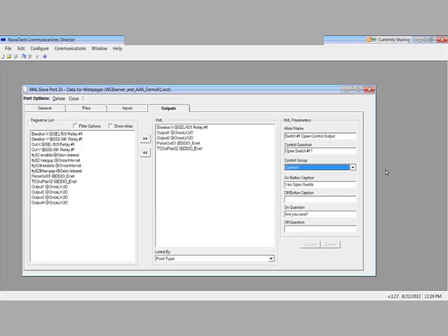And we could go into that in a little bit more detail, but each user that's set up on the OrionLX has a collection of privileges. Some of those privileges are, do I have the privilege to control a device on a web page? And this is where you set those control levels. Here's the dialog box here, yes, open switch, are you sure? So I put those parameters in there. You can have them appear in a customized way on the web page.